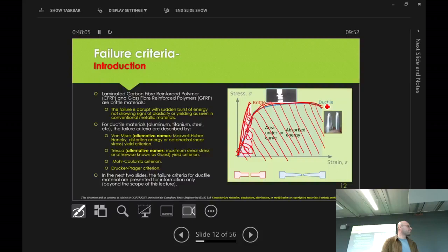Yeah, go ahead. For something like bulletproof armor, like when they use Kevlar composite, wouldn't you want something like high energy absorption? Yeah. When you said that composites aren't that good at it, CFRP is not good at it, no. Glass fibers are better than carbon fibers.